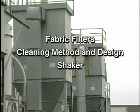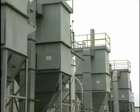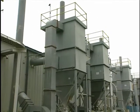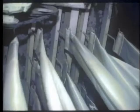As the name implies, shaker collectors clean the bags by gently shaking them. The shaker collector has a tube sheet between the vertical casing and the hopper. The open bottoms of cylindrical bags are attached to holes in the tube sheet, and the closed tops of the bags are attached to the shaking mechanism in the top of the casing.